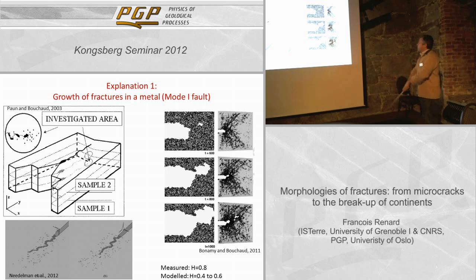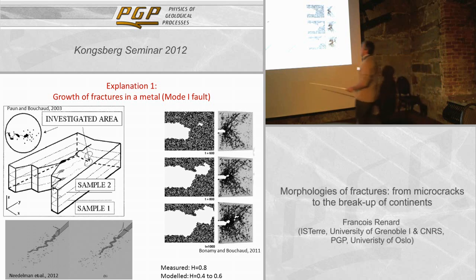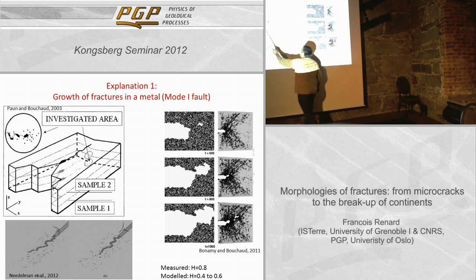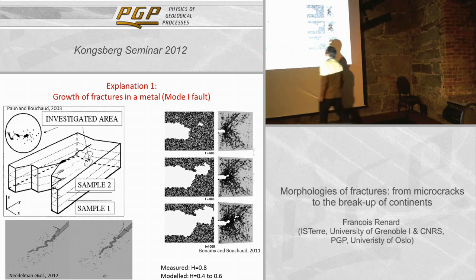And there are some experiments and simulations which see this kind of effect of the presence of damage. So that's a kind of experiment where you have a notch, 2 pieces of, I think this one was a metal, and a crack propagating. And this crack propagated, and it becomes rough, because it started to create its own damage, some cavitation in front of the crack tip, or just meeting some heterogeneities.